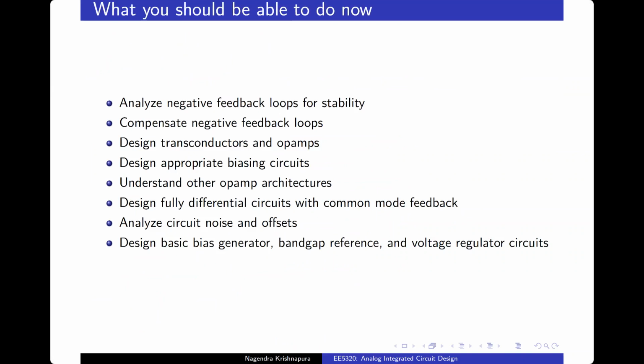First of all, by definition, the small signal analysis means there is one operating point, and after that, there is no further change there, right? That is, you calculate the small signal parameters at that operating point. So if you are considering, first of all, threshold voltage change, I don't know, you probably mean by body effect or what is it? Yeah. So that body effect itself can be taken as some incremental quantity. I mean, VSB can be taken as some incremental quantity and you can do incremental analysis. Or of course, if you are considering it as change in threshold voltage, that is basically like large signal analysis, right? Completely dependent on the problem, right?